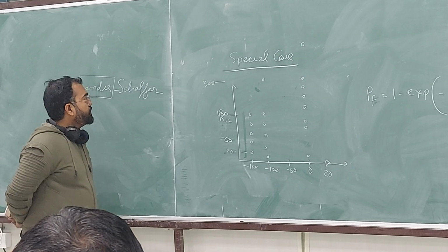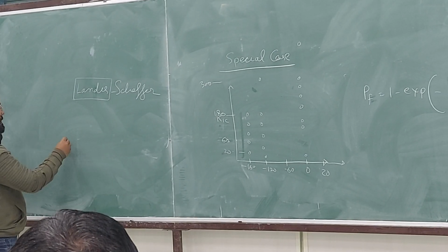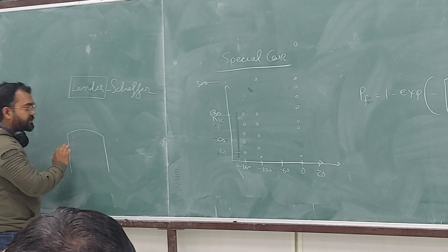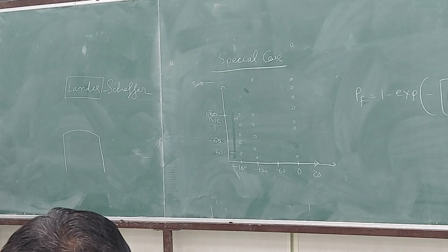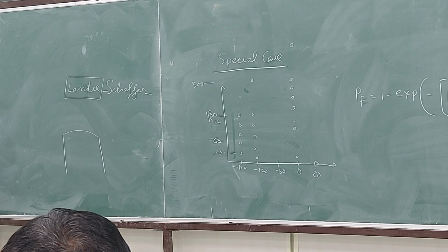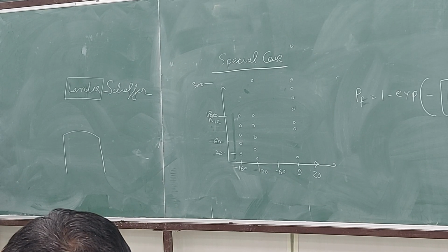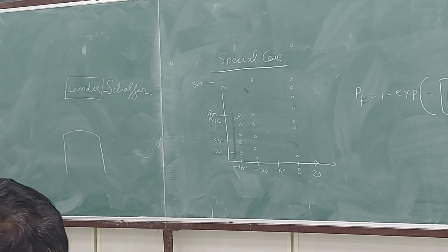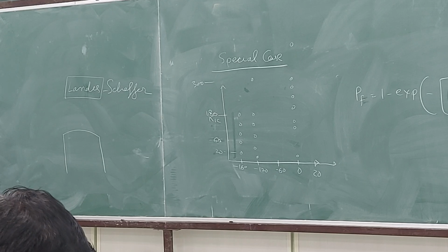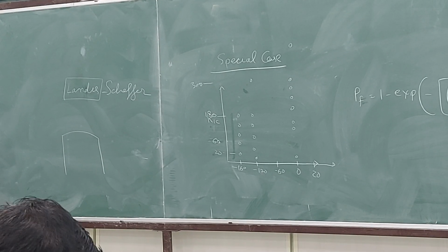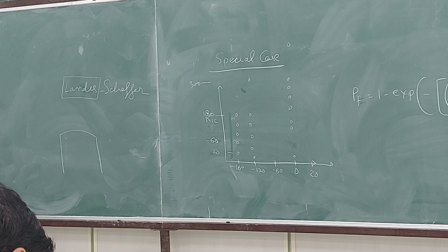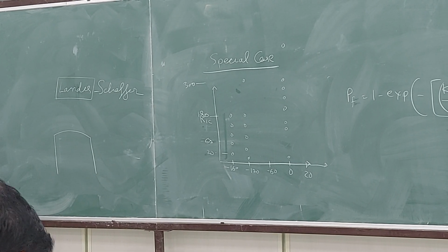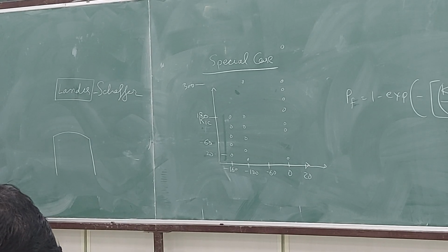Okay, so what they found was, suppose you have a crack front, and the crack front is really not straight. We will discuss in some class why it is not straight. Well, one reason is that you don't have a complete plane strain situation. So wherever the stresses are higher and the constraint is larger, the crack will propagate more, because it doesn't have any possibility of flow. If too much constraint is there, then it must break.